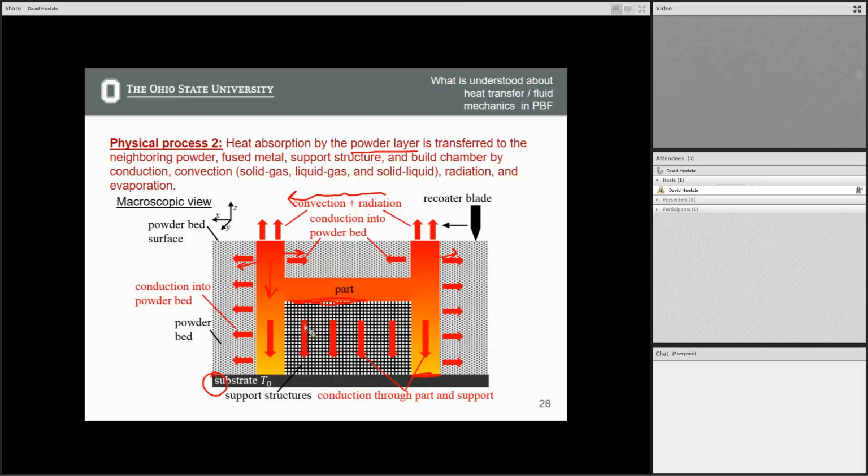I think the closest thing to what you're asking is that people have looked at chemical treatments. The chemical treatment will attack everything, but if you have a very thin member, such as the interface between the part and the support, it'll eat everything equally, but a thin member will eat through quickly, where a thick member will take forever. So you can basically time how long you're etching that part, and then the support will fall off. But that's not current practice. There's just one professor at Arizona State that does that. And he's trying to get it to take off, but I don't know if it will. But it's a major problem.